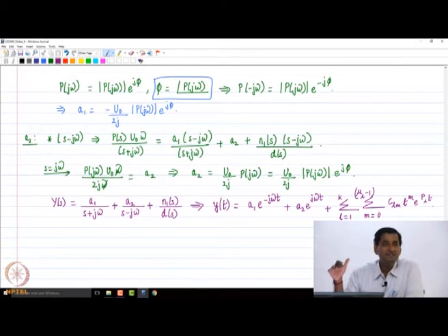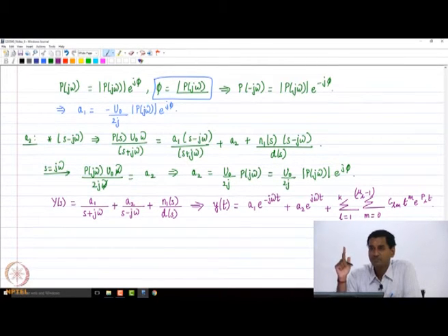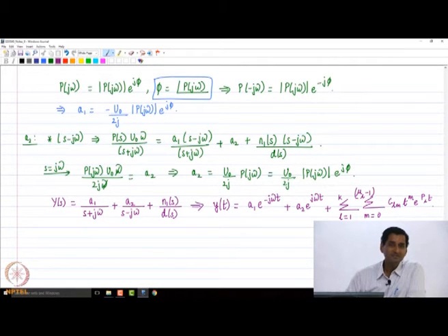The main thing is that we are going to have the poles as the exponents. If you recall, we did this when we analyzed stability, and this is the result where we used to figure out that if my poles lie in the left of the complex plane, the system is going to be BIBO stable. That is what we did some classes back. So essentially I am just going to get the same structure. That is very important as far as this is concerned.